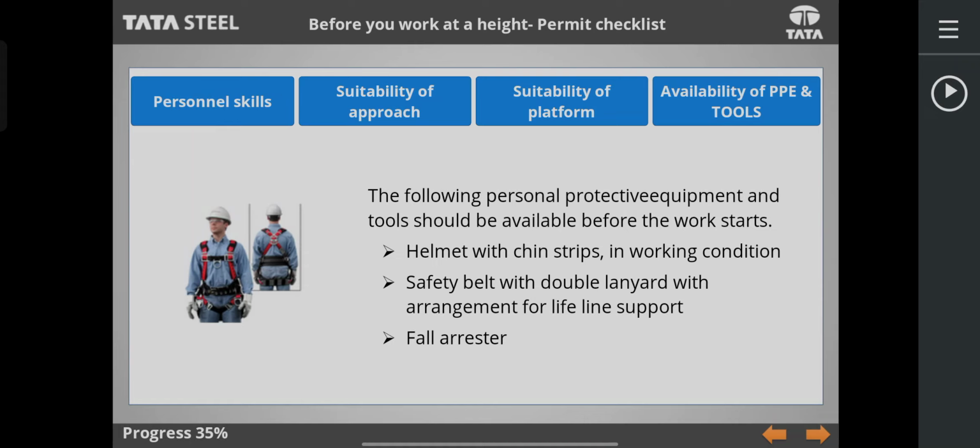If a manila rope is issued as lifeline or for any other purpose, it should be checked before each application when it is in use. The diameter should be ascertained before use and certified by a competent and qualified engineer of the department executing the job. The test procedure for manila rope will be the same as that followed for all other construction tools and tackles.